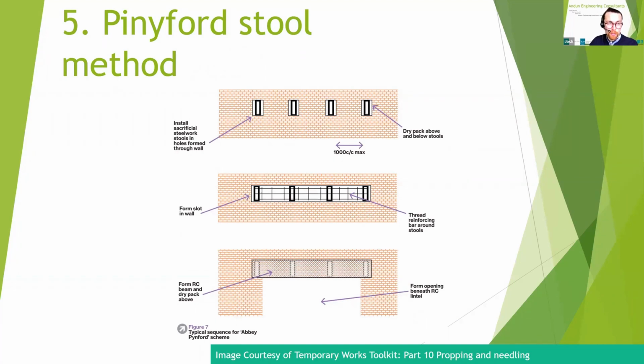Into this horizontal slot, which has gone throughout the wall for the new lintel to be placed, that's made, and then the rebar is placed into that void, ready for the new lintel. Shutters are placed around the slots, and then the concrete is cast.